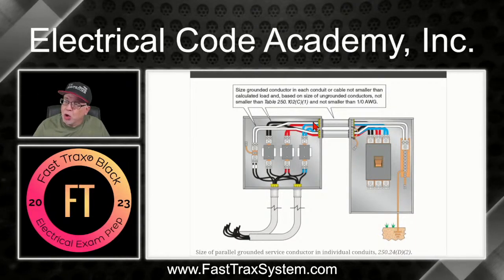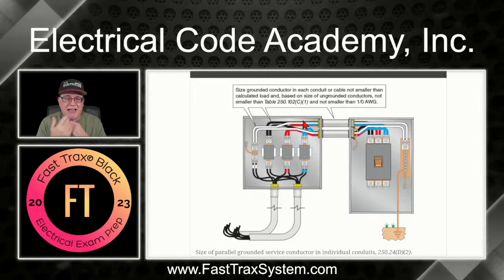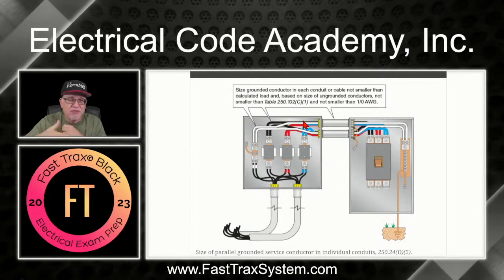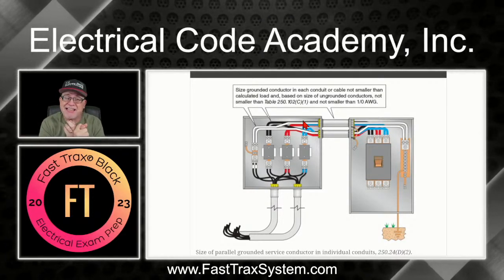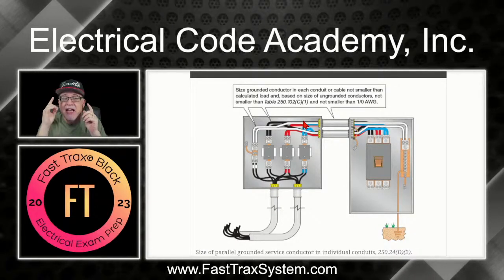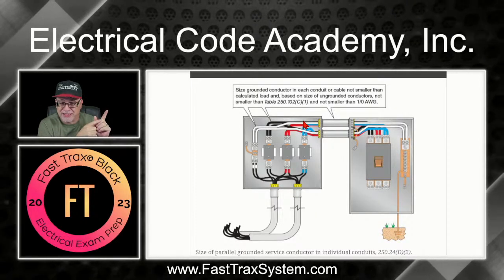Now remember, we're running these in parallel, so you automatically know that it can't be a 2. It would have to be at least a 1/0. But we're just going through the motions, and that's how you would go to the table, okay? That's why I tell you, don't forget the paralleling rules, because they can come back and bite you in the butt. Even on an exam, if you're taking an electrical exam, it most certainly could bite you in the butt.